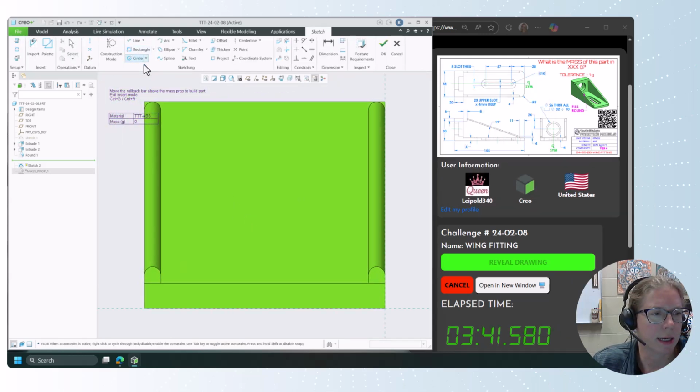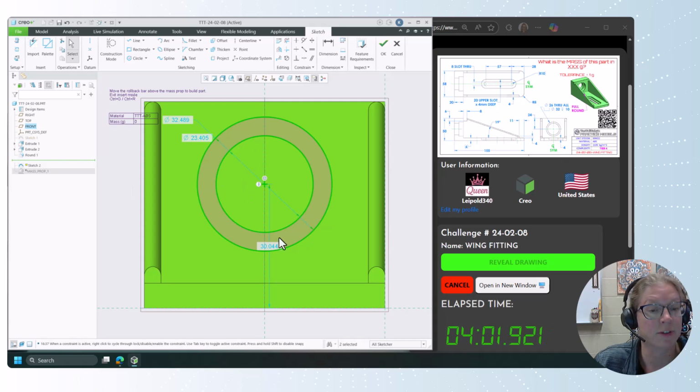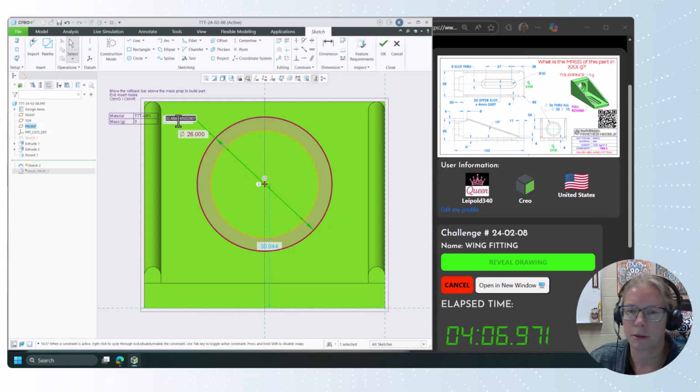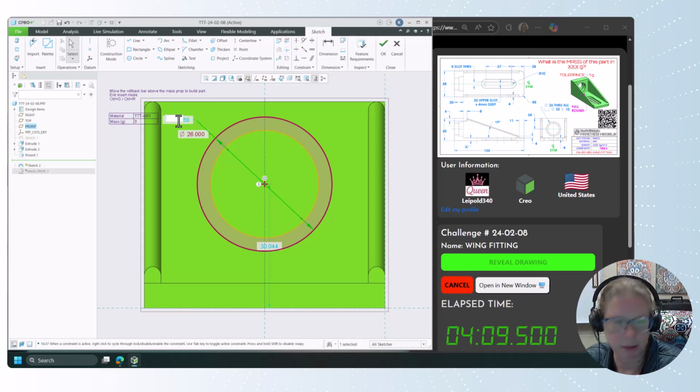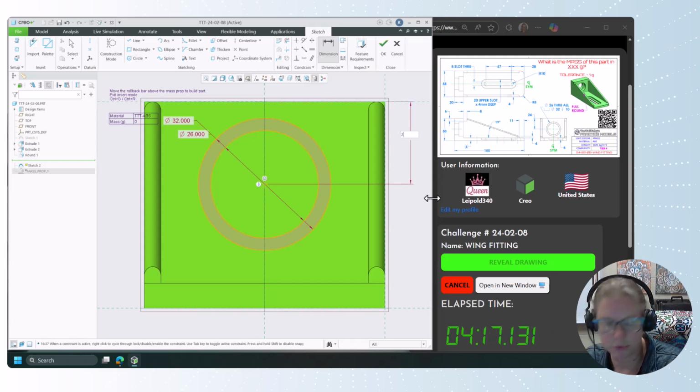Okay, and we're going to add some circles. Interesting. Where's my front plane? All right, let's drop my plane on. There we go. Oh, if I hold down Alt, I can select things to be references on the fly. So that wasn't popping up for me. No problem. I can invite it to the party. 26 is my center hole. 32 is the counterbore. It is located from the top, and that is a depth down of 24.